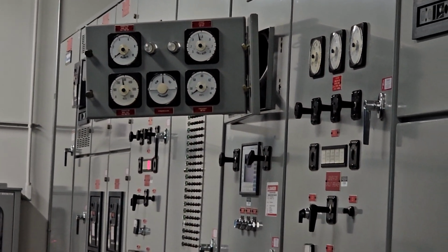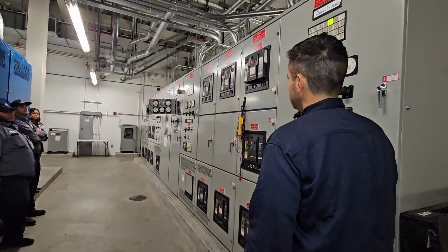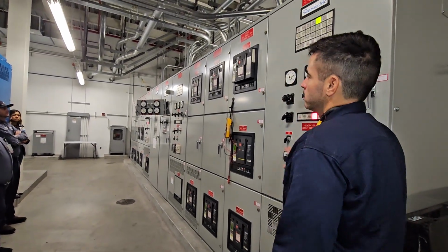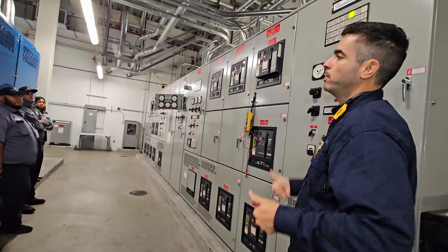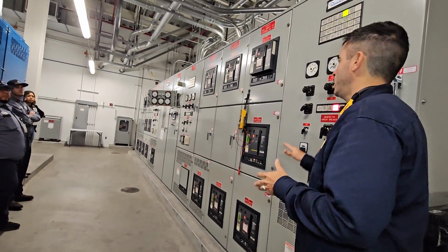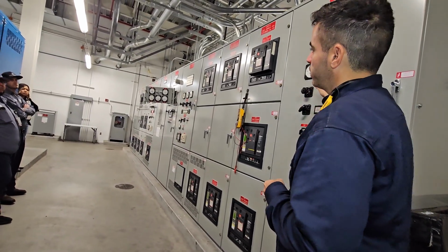Try how it works. Okay. Questions so far? So under a manual condition, you lose the PLC. This is the way to bring both engines online. And as long as you have it in the run position, that's very important. Keep it on the run position.